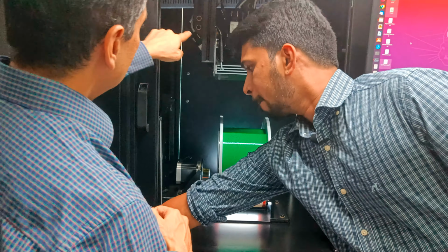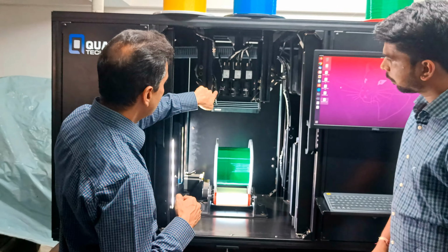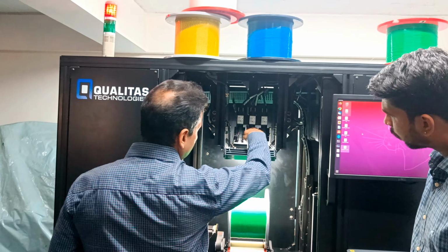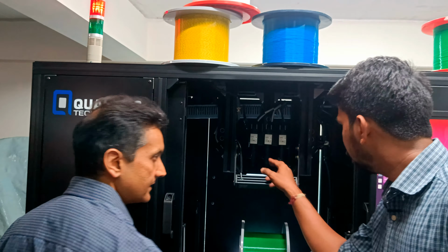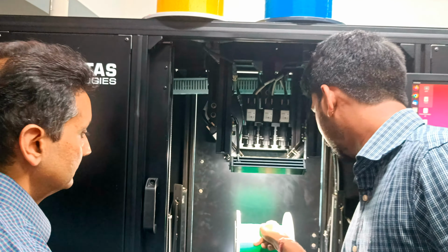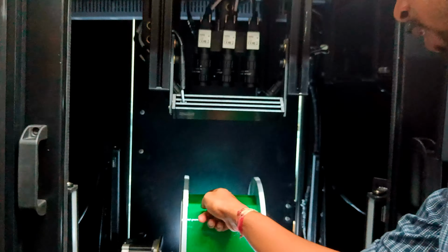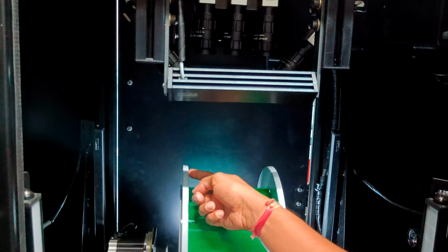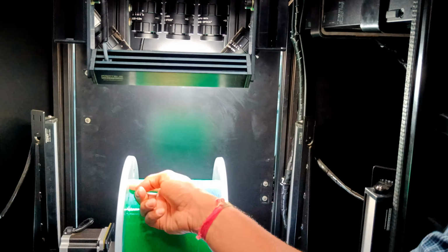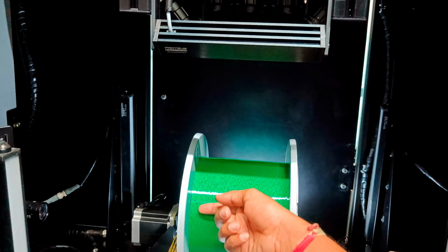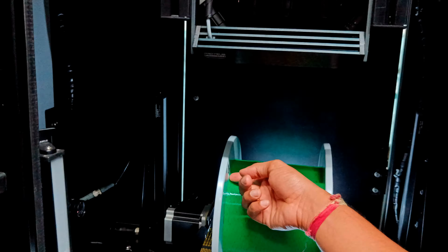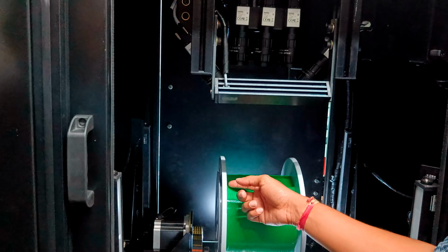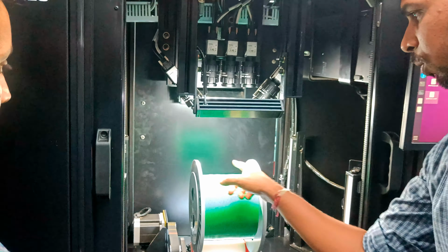All right, so now, we have 3 cameras on the top and then 2 on the side. So, I assume these 3 cameras are looking for the dust? The 3 cameras from the top will be covering the fiber as such, if there is any dust or any particles that might come over here. And these 2 cameras are looking at the flange and also the fiber, if there is any loose fiber that might come here, because typically the issue comes near the flange itself. Most of the defects come near the flange. So these 2 cameras will be looking at both the flanges.